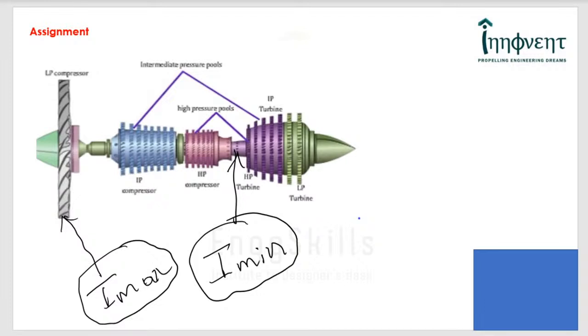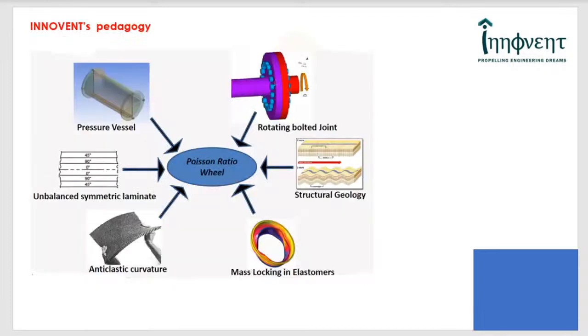Now I spoke about so many aspects, right? In the beginning I gave the example of the bearing support structure, and I emphasized that a single component can have several consequences. The bearing support structure not only influenced the rotor dynamics and the engine vibrations, it also influenced the tip clearance, and I told you tip clearance is a very important parameter, not just for the compressor and turbine performances. It can also affect the surge margin, that is a very important aerodynamic margin of the compressors.